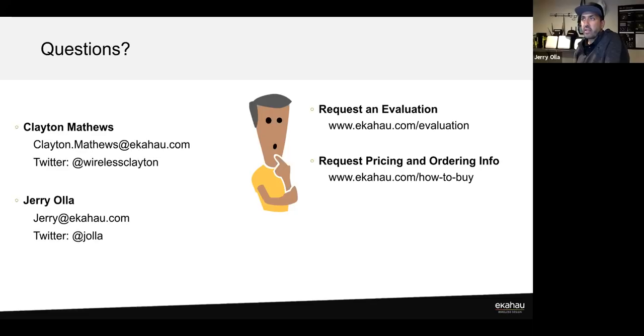I'm sure somebody in chat can explain it a lot better than I can, but usually where I see RxSOP being played around with is in very dense environments, like stadiums and things like that, where you're really fine-tuning things. There's a cost, where you're basically inducing additional interference, which could equate to higher retries and higher noise in the environment, at the cost of giving the AP more transmit opportunities. So Bruce says it trades transmit opportunity for SNR. That's really the simplified way of explaining exactly what I was just trying to explain. So thank you, Bruce, for that.